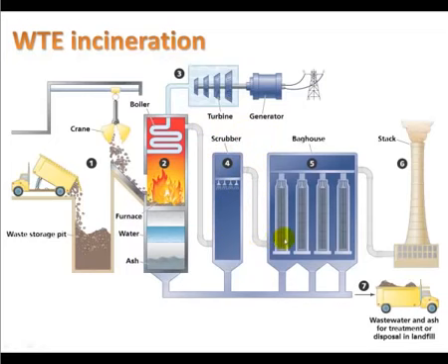They first go through a scrubber, a wet scrubber, which knocks out some of the pollutants, and then from here it goes into a baghouse for particulates. The baghouse is where we can capture particulate matter, so we can capture the ash, and then that ash can go to a landfill, and ultimately whatever has not been collected as ash goes to the stack to be given off as air emissions.